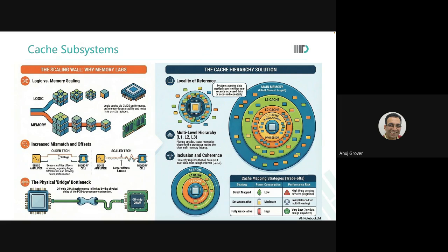And those of you who will go into GPU teams or into processors with Qualcomm and others, they use tightly coupled memories in their mobile application processors. NVIDIA GPUs use tightly coupled memories. Apple neural chips also use them. So tightly coupled memories are fully associative, but they are kept very, very small. Just 128 words. That's sufficient for them.